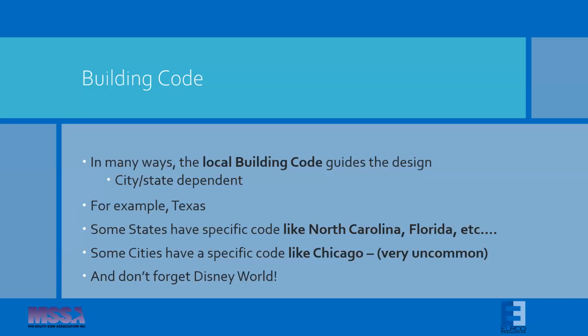So why does this matter to you? Basically, a sign that you build in one city may not be properly designed for a nearby city. The most stark example of this is where the 2009 building code is still in play versus the 2012 version. Very different analytical approach, and so you actually get slightly different results. And so what is per codes in a 2009 IBC city may not meet codes in 2012.